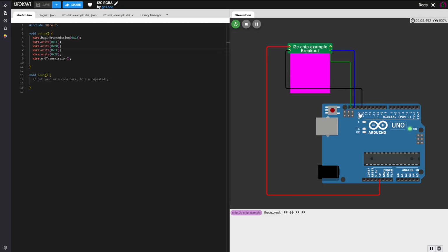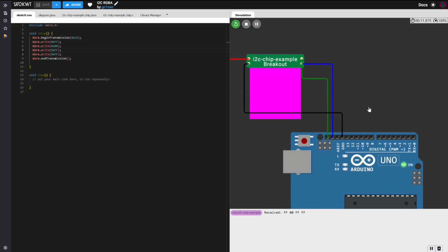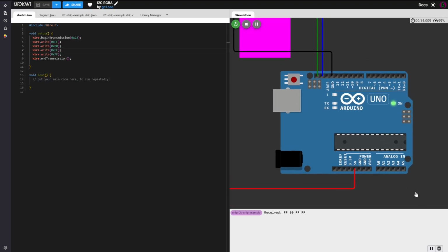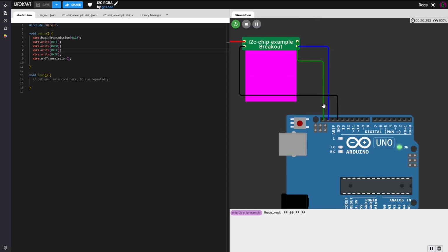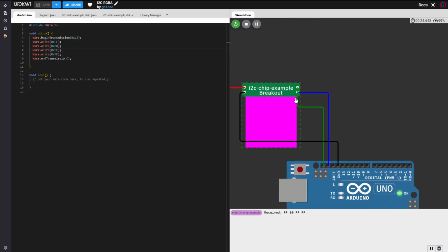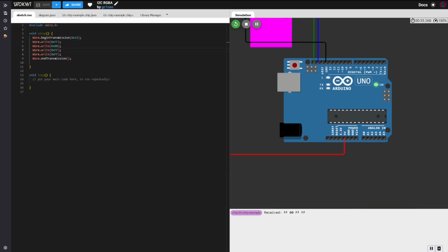We've got our SDA lines. I've had it connected up here at these 2 pins that are above AREF. It does work in Wokwi. Otherwise, it would be 4 and 5 down here. So this would be 5. Mind you, these pins are connected to those down there. So we've got data on 5 and clock on 4. Those are the pins to use for the Uno.